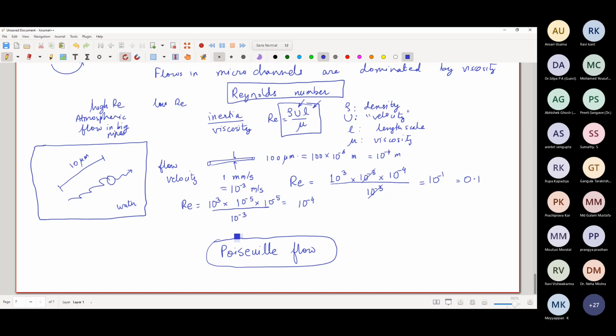Sir, one question. While deriving the momentum equation, you have considered pressure only as a surface force, but you have not considered any stresses so far. No, it is correct. I have not explicitly mentioned stresses, but the viscous stresses are manifested through the viscosity.